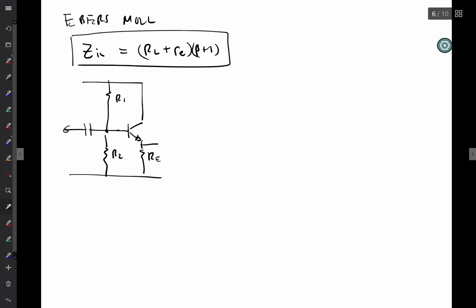Now it gets a little bit more complicated because if I think of this piece right here as comprising the core, that core gets added an additional parallel resistance of the Thevenin equivalent of the bias network. And if you're not close to signal frequencies, you would have to have the impedance of the capacitor in series with that. Most of the time, you can ignore this. But very often, you cannot ignore this. This becomes a big part of the input impedance.